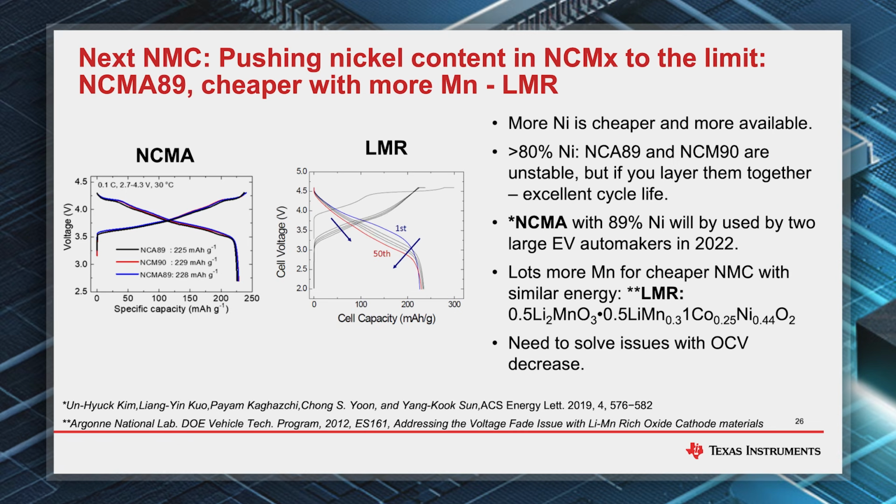But in this particular design, when it is combined with some small amount of nickel and some other dopants, it actually stabilizes the structure. And that results in a relatively high voltage, actually 4.5 volt as well, and potentially they can go even higher voltage, and decently stable cycle. So there's a lot of developments going on. This is actually one of the most researched areas right now because it promises the same cost as LFP effectively, but with the energy density of NMC. So you can think about that as a cheap version of an NMC with the same energy density.